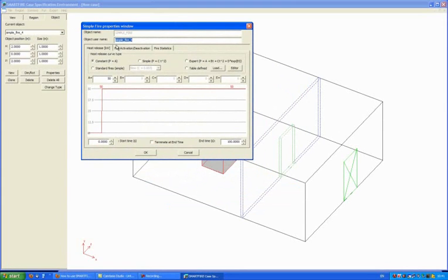Because we're using the heat release rate model, you see that the menu has a heat release tab. If we had activated the smoke module as well, there would also be a smoke tab here. Because this is only a heat transfer problem, we have heat release in kilowatts that we have to define by some curve. The default option is a 50 kilowatt fire that starts at time equals 0 in the simulation, and then continues for all of the simulation.